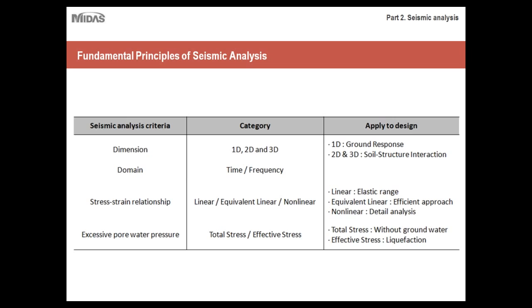Depending on the type of analysis you run, for example, if you were to run an analysis for how soil responds to seismic loading when it's drained versus undrained, the results would be very different. When soil is undrained and seismic loading is applied to it, that soil will actually behave as a liquid in a phenomenon called liquefaction.